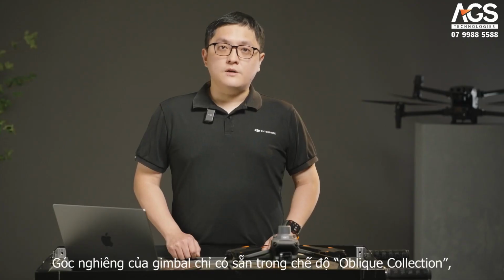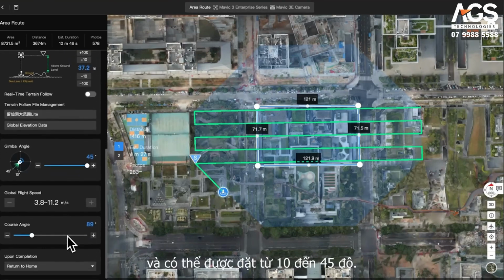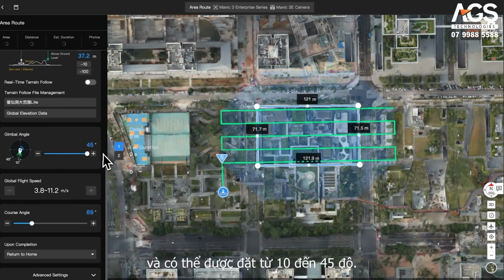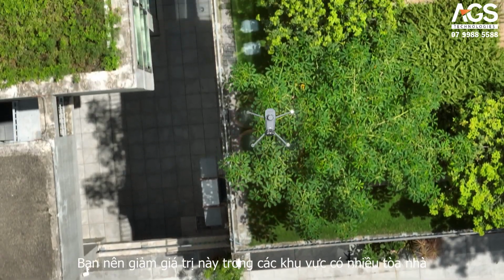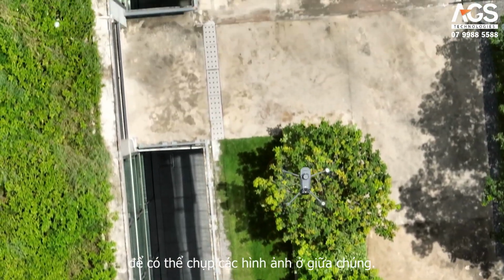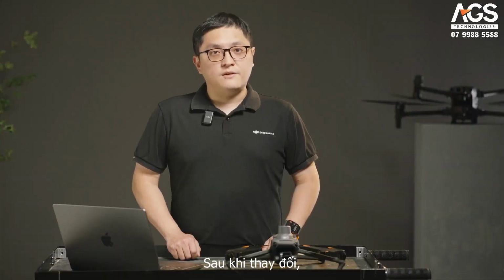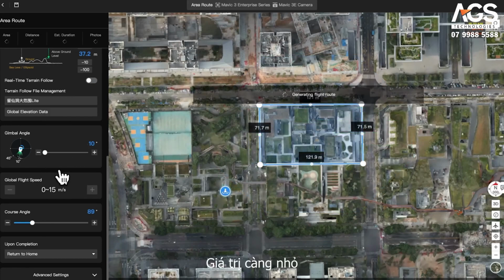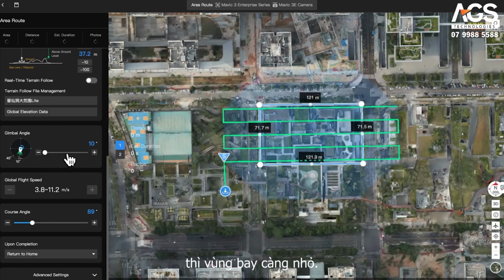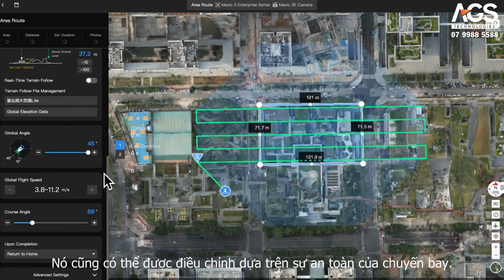The gimbal tilt angle is only available in oblique collection mode, which can be set from 10 to 45 degrees. It is recommended to lower this value in areas with dense buildings in order to capture the images between. After making changes, the flight route will be regenerated. The smaller the value, the smaller the flight area. It can also be adjusted based on the flight safety.